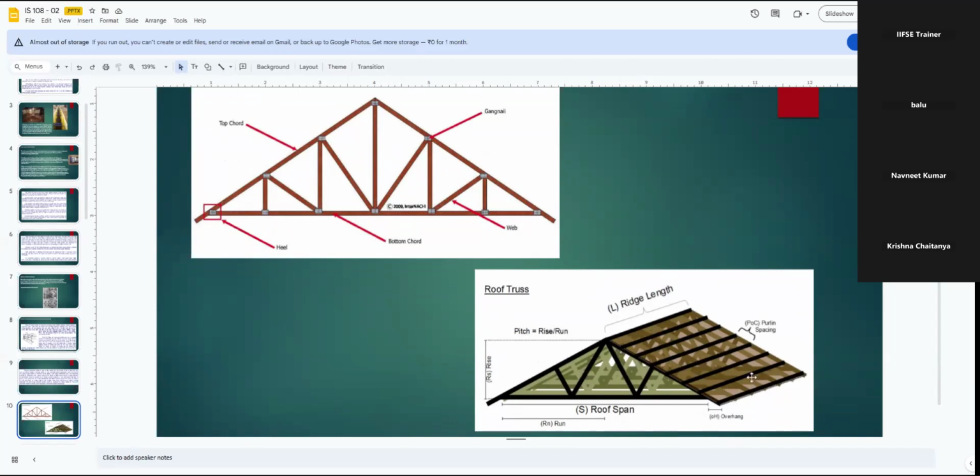So instead of a total of 8, initially you can have every alternate support. Only then you leave, or remove the belts which you have applied for the trusses. Otherwise, there might be a chance of the truss falling, resulting in people getting injured during the lifting activity.